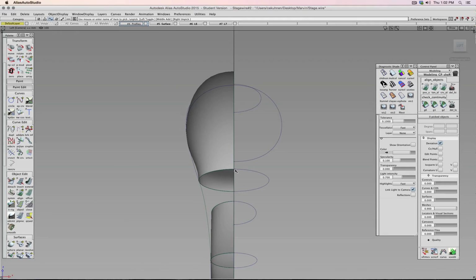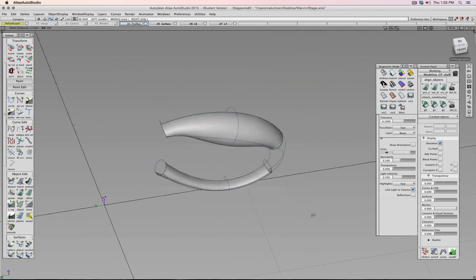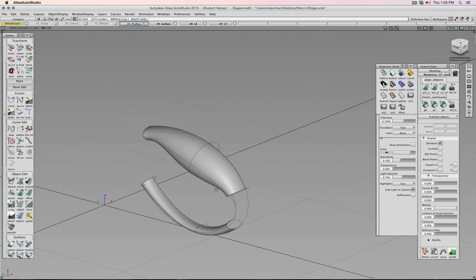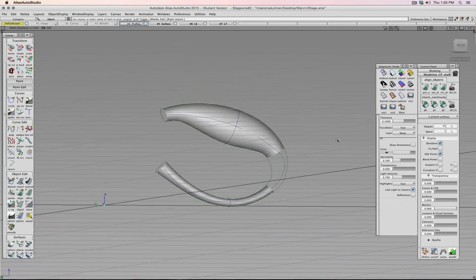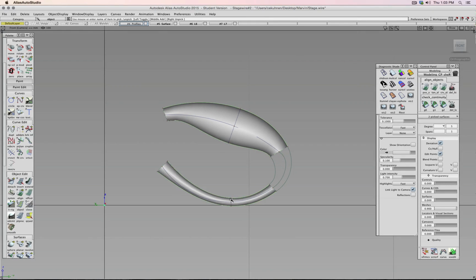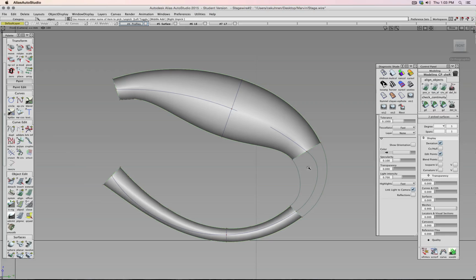The rail surface at the end kind of tries to stop here and tries to make a transition like this one. I don't know, maybe goes straight forward. That's the reason we have this dip, and this dip is completely messing up our blend. So this part we have to eliminate, because those are the curves we somewhat need. So let's see what we can do with that. Oh, also there, this is maybe causing a problem. You see how this one pushes down? Yikes, also here. This is not really good.